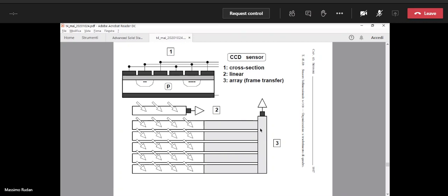Then the vertical CCD also has clocks. They are operated, and the charge packets are transferred vertically, bottom up, into the single reading circuit. Again, we have only one reading circuit. So we have total uniformity of reading, no noise, and very little space consumed by the reading mechanism.